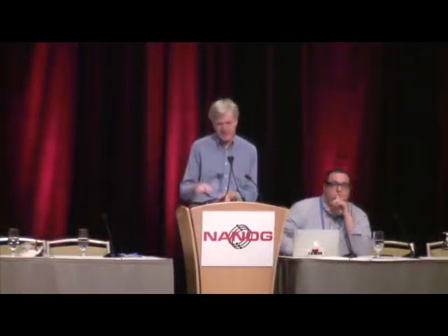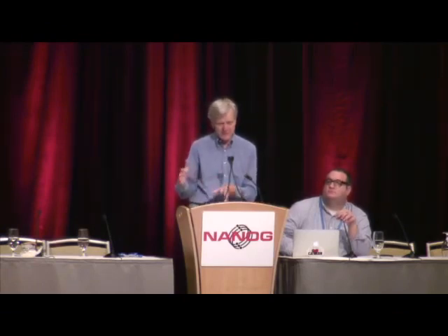So would your assertion be that they're so small to begin with, any additional slight changes or fixes such as DBL or things like it really wouldn't be of any net benefit? No. So what happens today is the big buffer designs use DRAM and just vast amounts of DRAM to over-provision buffering. The small ones are so small that you couldn't actually allocate the buffer on a per flow basis because there's not enough buffer for these flows. So it would work with a medium-sized buffer, but that doesn't fit on a single chip today, so it's not being used today.